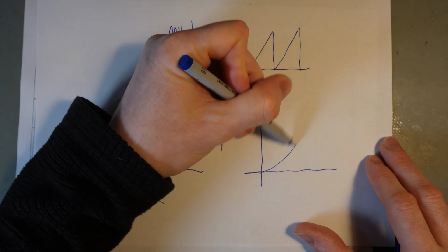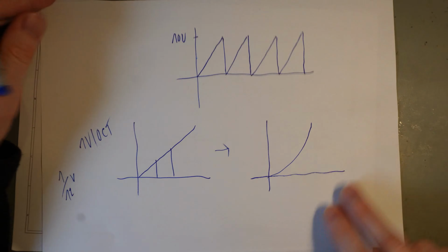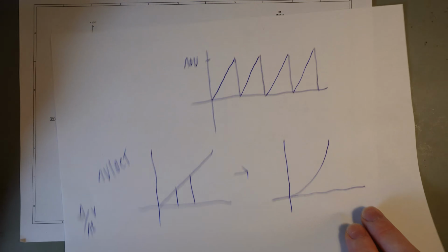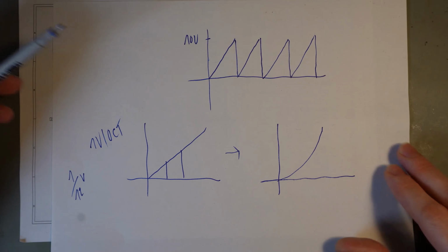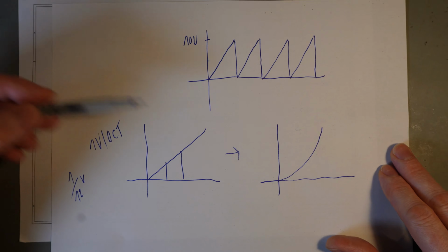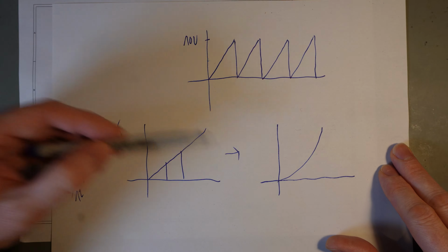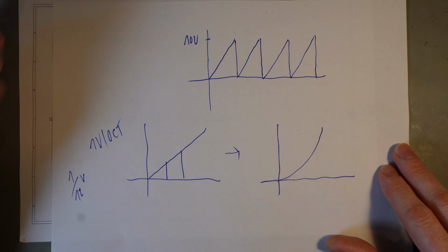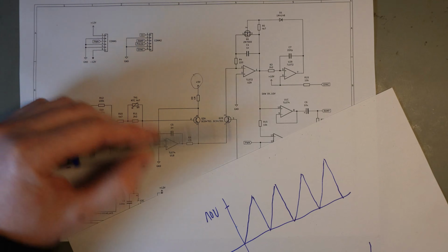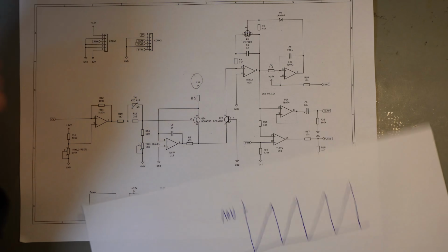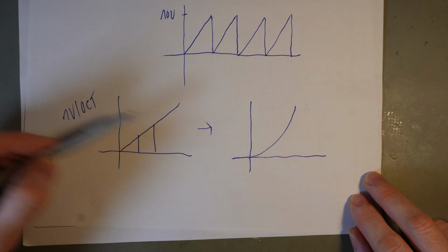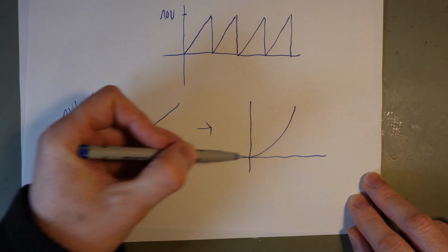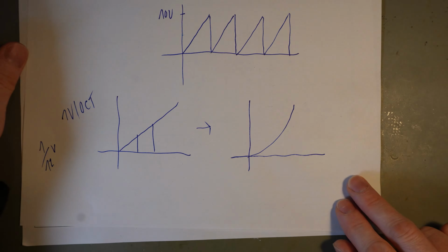to an exponential one, because in every succeeding octave, the frequency doubles. So what we need to do here is we need to convert from linear to exponential. And the problem here is the converter needs to be very precise because we want to have a good tracking over multiple octaves. So this means we need to stay on this curve here very precisely.